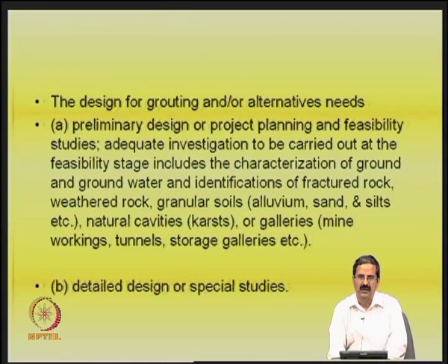So, for example, if you are trying to characterize the area in a rocky slope, you would like to see whether the slope is stable. And whether it has any underground water resources, perched water or whatever. So, one should be able to understand what exactly is the type of rock or soil, then understand the water table levels and all that, and the identification of fractured rock. If fractured rock exists, it leads to stability problems. So, how do you fill up all those fractures, cracks, joints and all that?